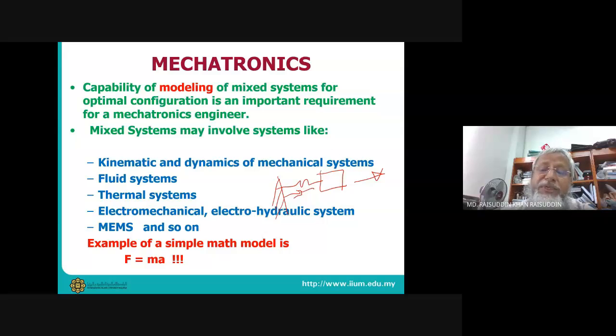So in the first place, representing the system, this is basically the representation of a car, how a car is moving, vibrating in the vertical plane. In that case, the mass of the car is here. The supporting springs provide damping, and it has a shock absorber, which is called the damping coefficient. So this is the way they are related. And you can see this doesn't look like the car. It is an abstract form, but this is really what we are looking for.